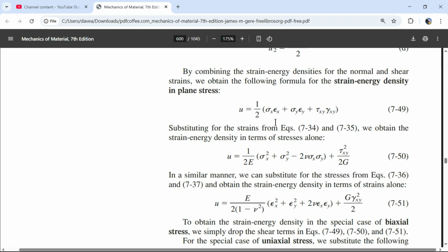And so if I have sigma y, I can get this as a function of just two other strains. And so I'm going to see how the strains square, and then we're going to get a Poisson's ratio. I said I could take sigma y as a function of a couple strains. I can take sigma x as a function of a couple strains. And so they're going to add very similarly. You're going to have this little beast, and this side won't change a whole lot, but we're just saying, hey, we want it in terms of the angle. This is the angle in radians, and this is shear strain, and we want it in terms of that. So shear stress is shear modulus times shear strain. So this is going to be a g on top times this squared.